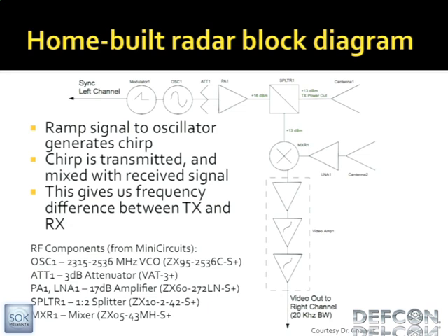And then there's this thing down here called a video amplifier, and what that does is it takes that really small signal and amplifies it a bunch of times at low frequency so we can feed it out to the computer. And there are 2 outputs to this. One of these is the sync pulse, which basically tells us when the chirp starts, and the other one is the actual data signal back out. And then I guess the components are here. You can get the slides later.